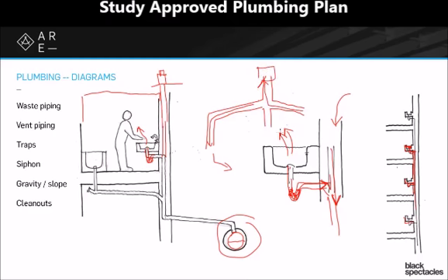Now, sometimes when people talk about this, they say, really, if you just have the open sewer going up to the roof, doesn't that make everything smell bad? If you actually go up onto a roof, you can usually smell it a little bit. You can tell there are vent pipes that are connected to the sewer. But because you're up on the roof and the wind is blowing and there's big open sky, it doesn't really matter. It doesn't build up in any way that would be uncomfortable for anyone, unless there's a very peculiar way that the air moves in that particular space. So in general, it's not a problem at all, but it would be a problem if it was going into a room, if it was going into an enclosed space, or even potentially a courtyard.